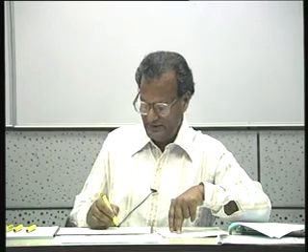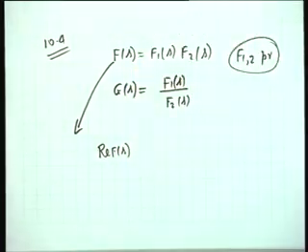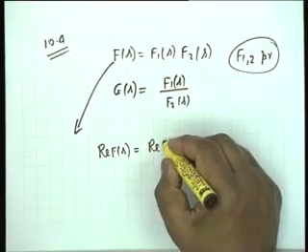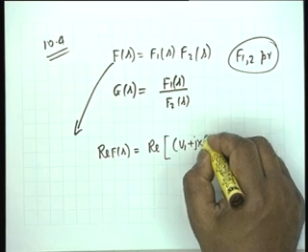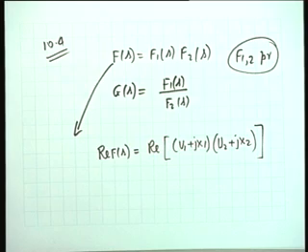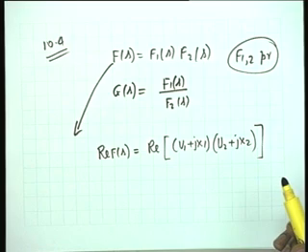But even if the product does not have a multiple pole, there is this real part consideration. Suppose real part of f of s, taking the complete right half S plane now. I don't have to go to the special case. It can be proved in more general terms. Real part of f of s is the real part of the product of the two. Let's say one is u1 plus jx1 and the other is u2 plus jx2. All that you know is u1 is greater than or equal to 0 and u2 is greater than or equal to 0, because f1 and f2 are PR.